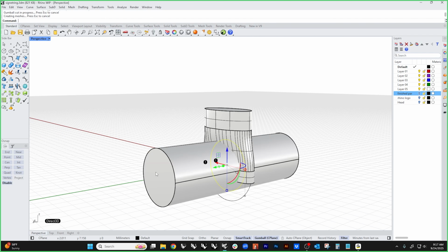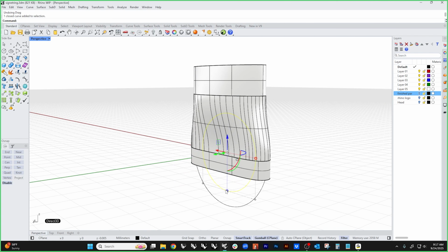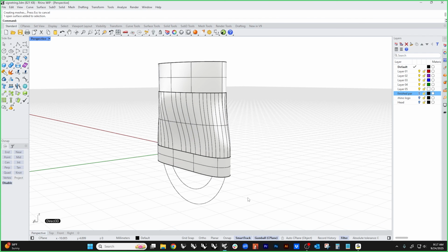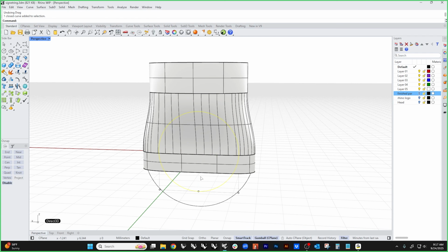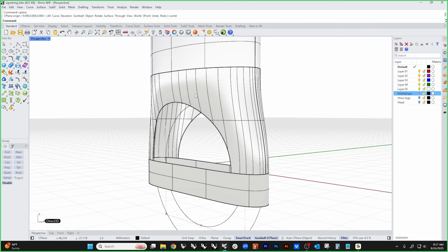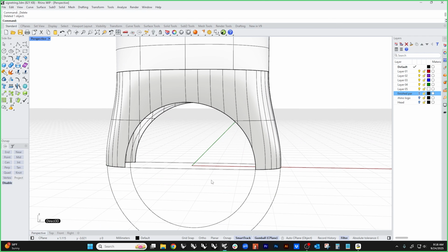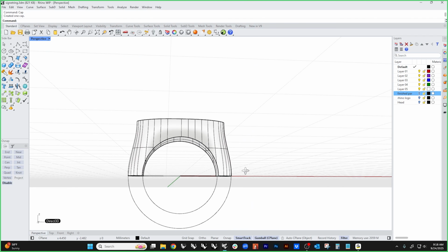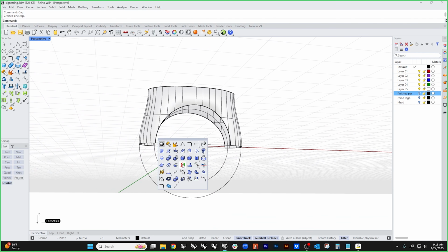If we take and use the gumball as a cutter, whoop, let's cut it in both directions. It doesn't want to cut that, that's fine. Let's trim that out. Now our five-sided surface is not a problem. It's done. We can delete that. We can delete that. I can run the cap command on that. And we are just about done, right? It's the world's shortest demo. 18 minutes. Thank you for coming.